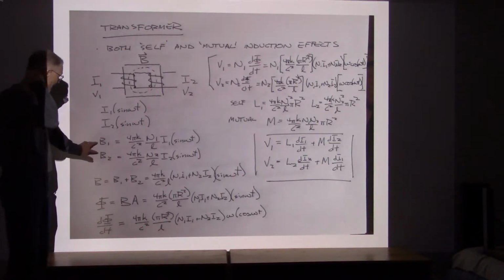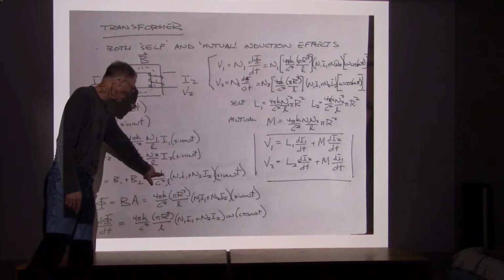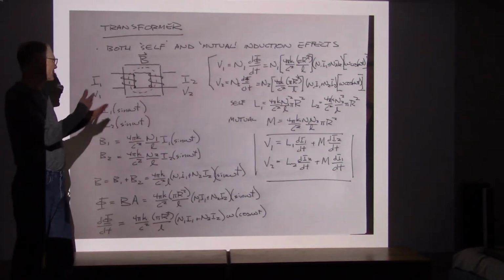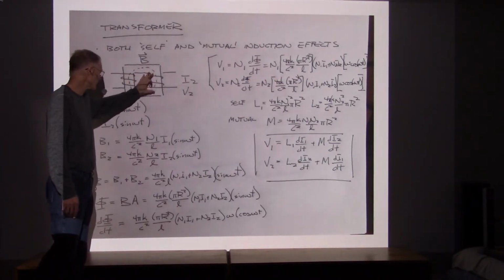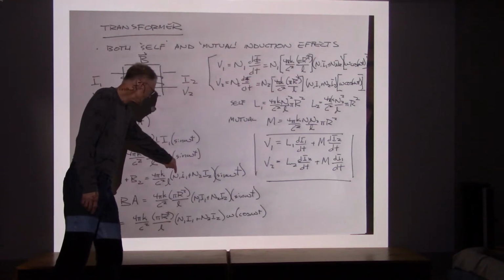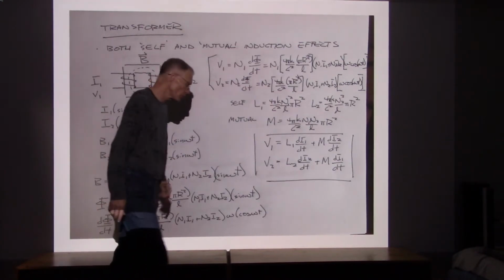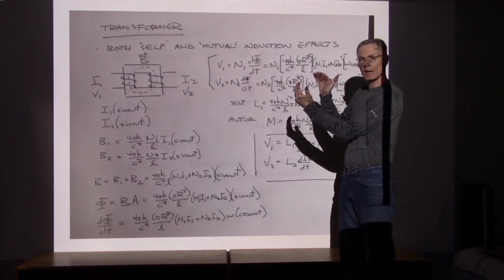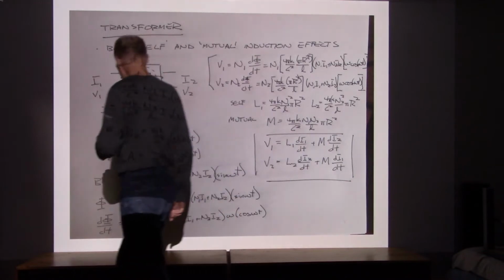When I add the two magnetic fields together, I get a common set of factors, 4 pi k over c squared, divided by L. Now, it doesn't have to match on the two sides, but we might as well say that L here matches L here, and that'll keep track of a factor of L. What I'm left with then is N1 loops times current 1, N2 loops times current 2, and then since the two sides are in phase, we'll have a sine omega t factor on the end.